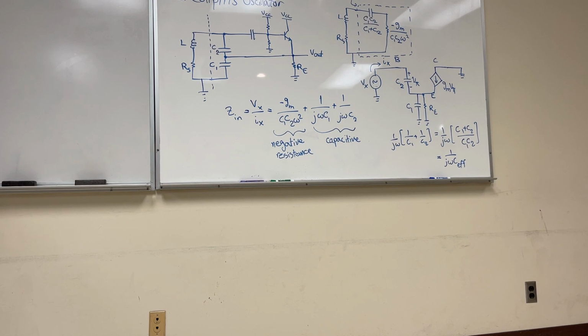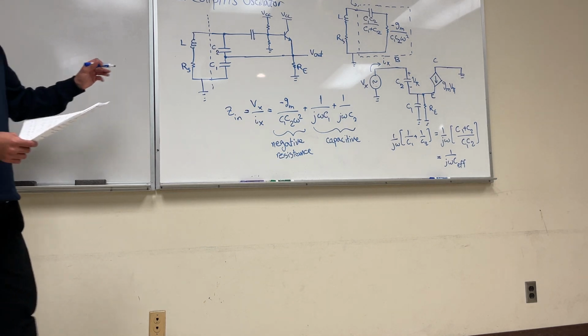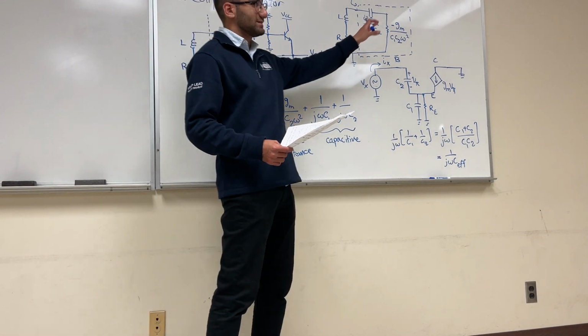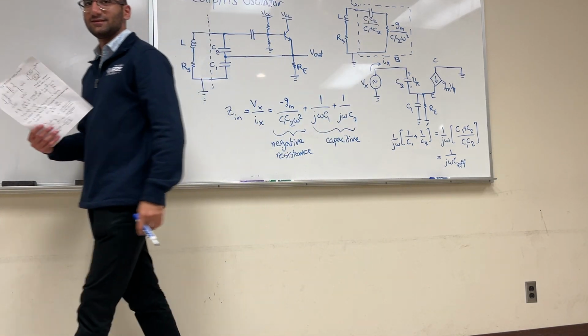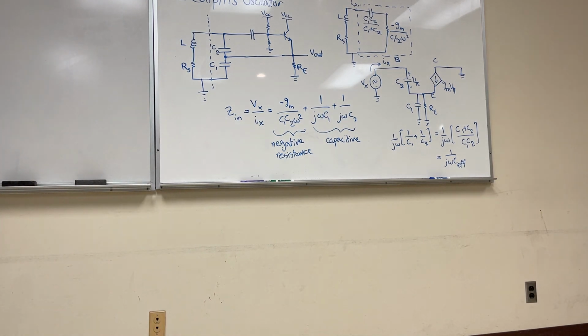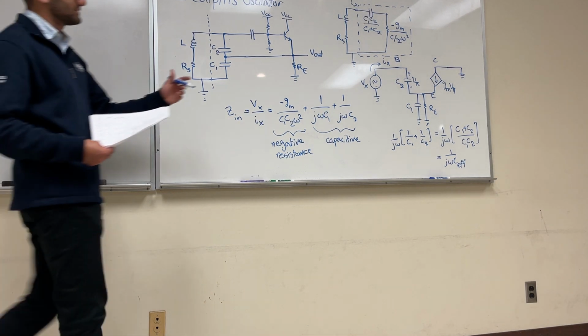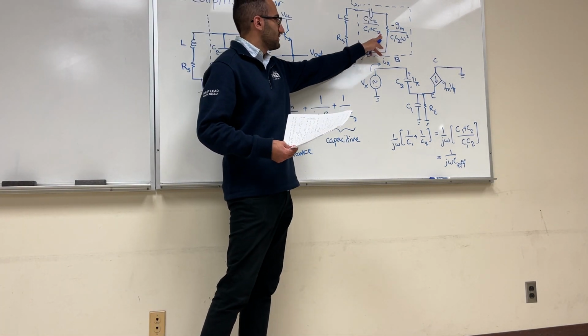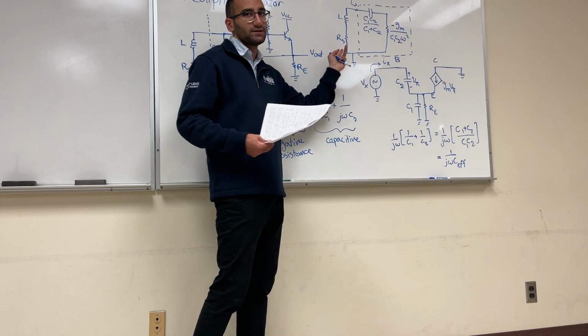If you have the negative resistance be higher, then you'd be continuously adding energy. Yeah, but at some point it's going to stabilize, like any other system. So technically speaking, even if I have a negative overall resistance, this will still oscillate. And actually what we will do is that we want this negative resistance to be on the order of 5 or 10 times larger than this RS.